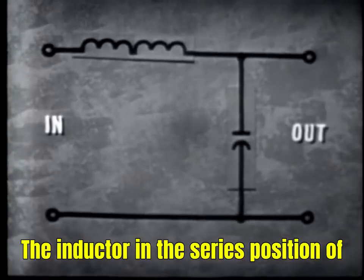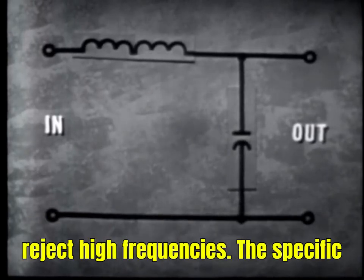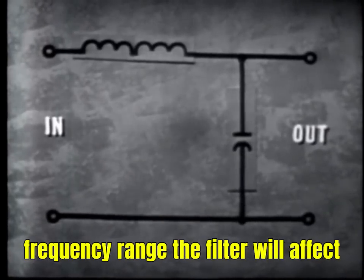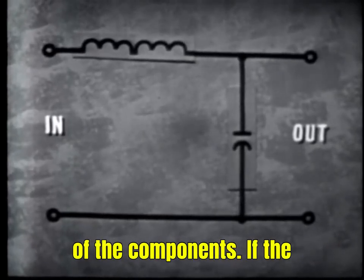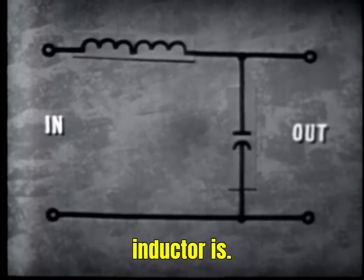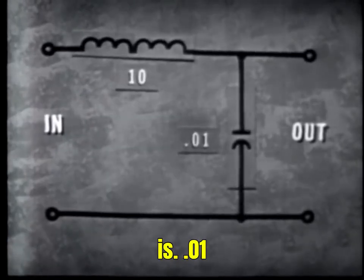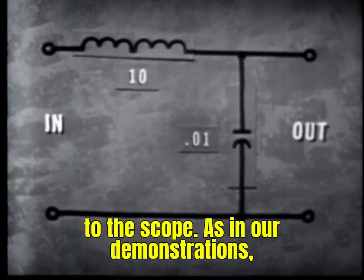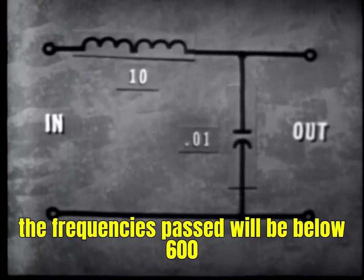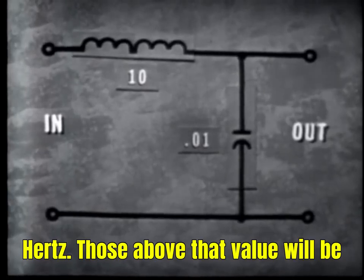The inductor in the series position of this filter will pass low frequencies but reject high frequencies. The specific frequency range the filter will affect will depend, of course, on the size of the components. If the inductor is 10 henries and the capacitor is 0.01 microfarads and the output is hooked up to the scope as in our demonstrations, the frequencies passed will be below 600 hertz. Those above that value will be rejected.